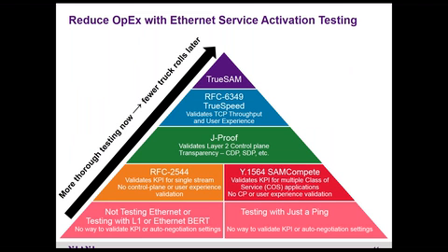So before we jump into the 2544 and 1564, we just want to make sure we're talking about this in the holistic context of testing these services. What we see a lot of customers doing, or service providers doing, is either not testing or testing with just a ping. And we really feel like that with the more thorough testing now, we can prevent a lot of the problem truck rolls later.